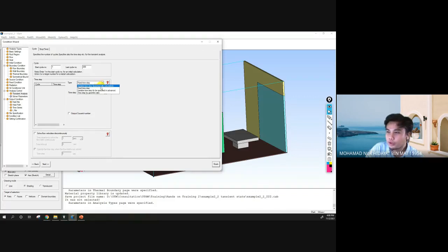However, you can ask the program to calculate automatically. This is automatically calculated for you. When the current number is 0.9, the best time step should be 0.01.